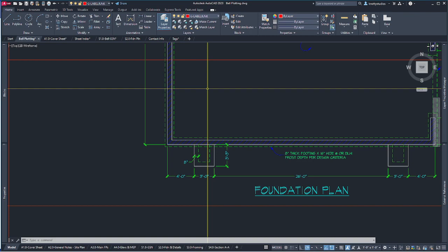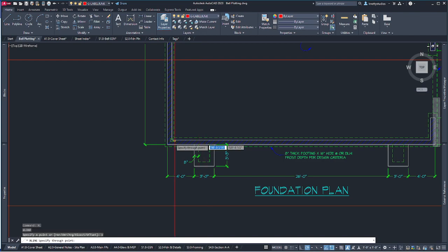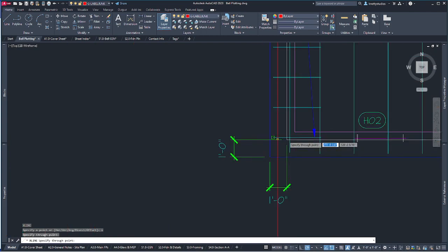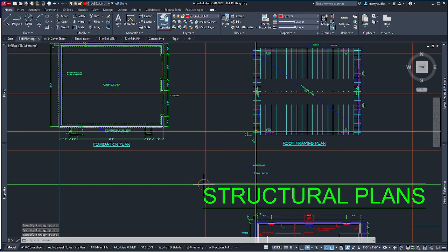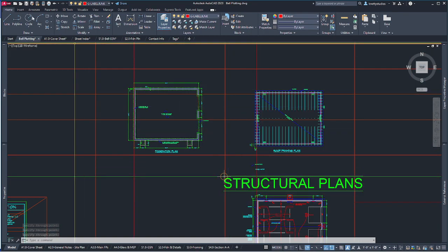They're just for us. So I'm going to do an X line, which is an infinite length. I'm going to do one vertically, so V, and then I'm going to drop it on what I call the baseline. I'm going to put one on the baseline over here, the outside of the framing. Those are the same point in the stack exactly. So now that that's there, let's save.